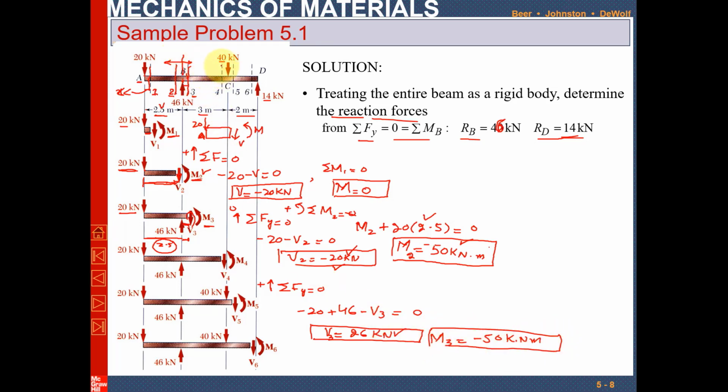Now you have to solve at point C by assuming that section 4 is before the application of the load, which is at point C. So you have to assume that this distance is very small. It means the distance of section 4 from point A is now 5.5, but it will be to the left. Similarly, you can take the section at point 5 and solve it at point 6. I will remove all this working and we'll see.